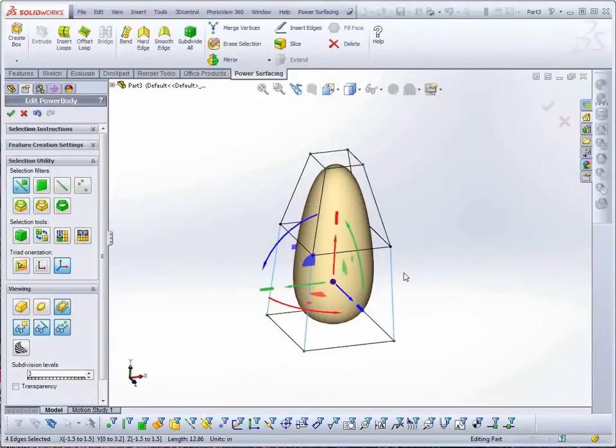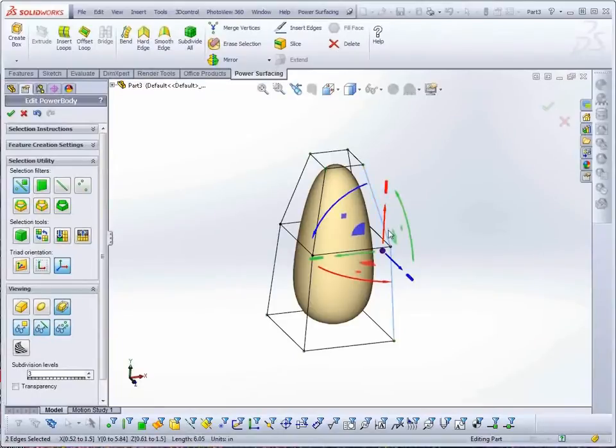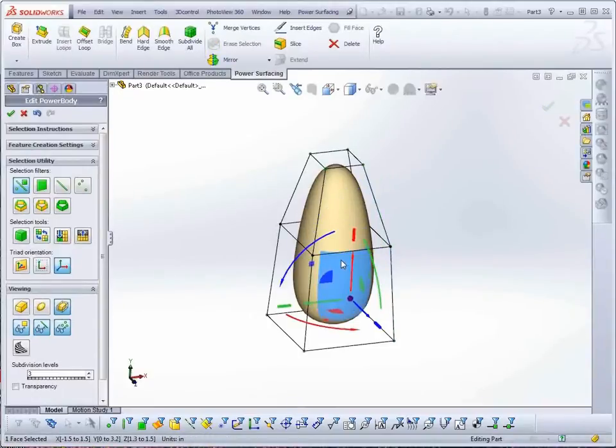In Select Any or Edge Selection mode, double-clicking in the center of an edge selects an edge ring, while double-clicking near a vertex selects an edge loop. With faces, the edge you select nearest determines which direction a face loop will be selected.